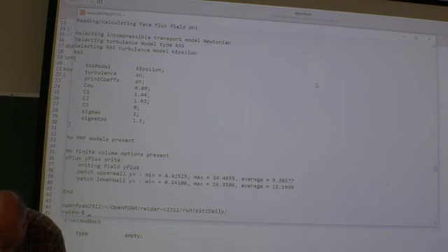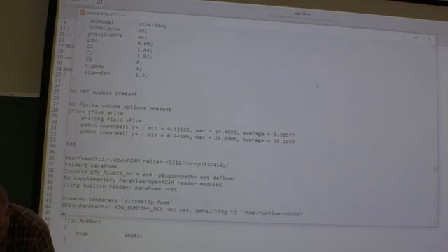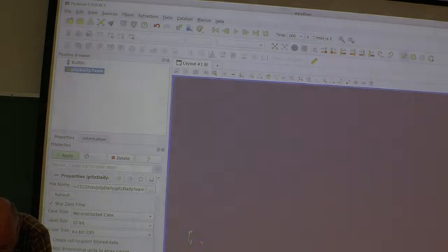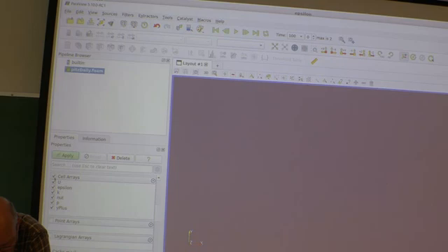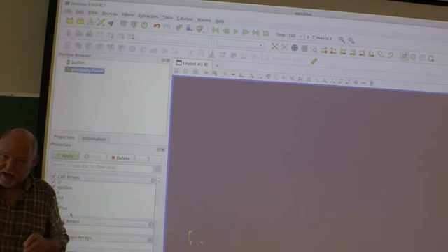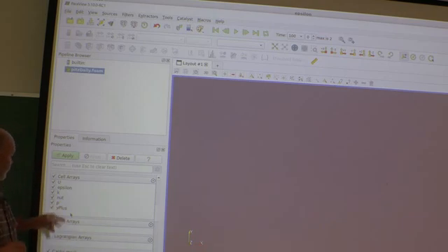So now let's have a look at y plus. By default, it should choose all your variables that are active in your simulation. So here you see you have everything, U and pressure, and then K, epsilon, eddy viscosity, and the y plus.